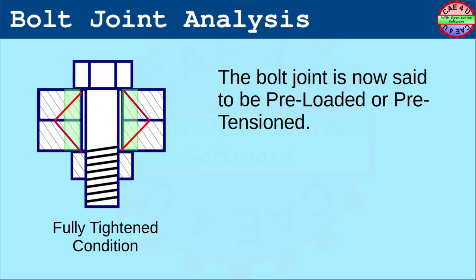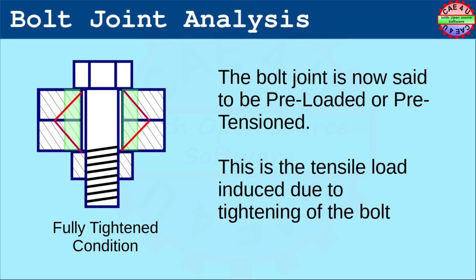Now the bolt joint is said to be preloaded or pre-tensioned. It is because as the nut gets torqued, the shank actually experiences the stretching. This tensile load is induced due to the tightening of the bolt.